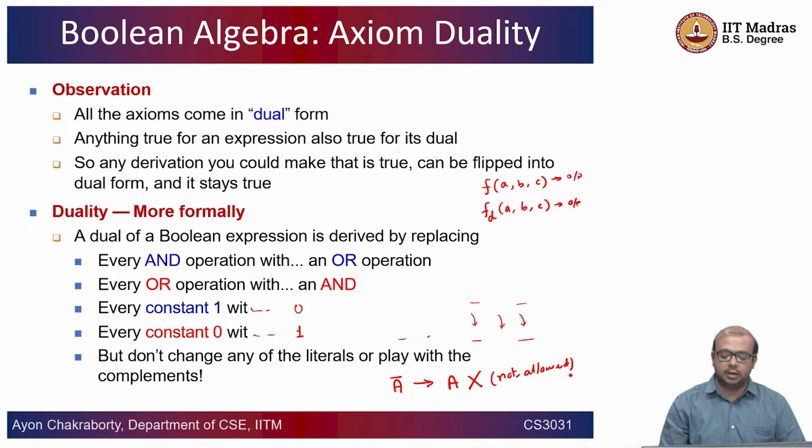Okay, and the good part here is that often you may require an expression that has more ANDs compared to ORs, or more ORs compared to ANDs. This is the thing that you can apply, and the reason I was telling you that you need more ANDs than ORs or more ORs than ANDs is directly related to how you design the hardware. So in your hardware you might be favoring more AND gates because of whatever reasons. It could be cheaper, it could be easily available to you, right? That will give you flexibility in the design choice.